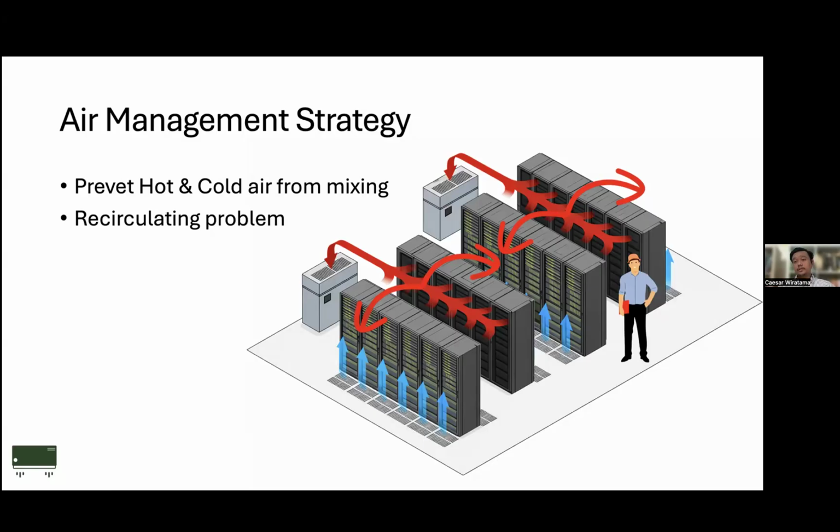The result will not be effective because we will get a higher temperature for the racks, which is not good for performance. On the other hand, if we have too much or too cold air that is not distributed well, we will lose a high amount of energy to cool the air, but not get a better result.